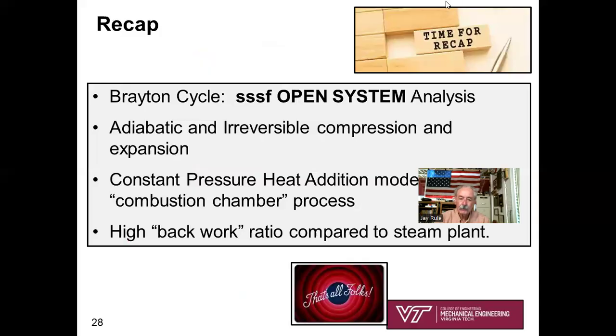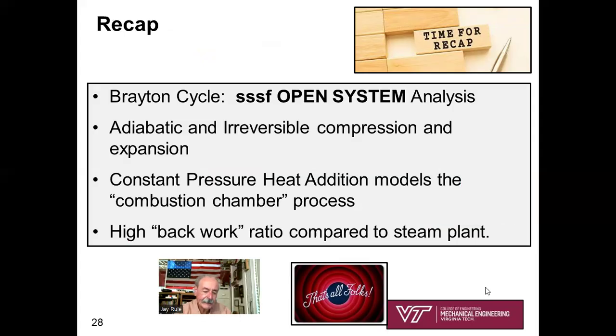So we've gotten to the recap of our gas turbine engines Brayton cycle. Recognize here that the Brayton cycle is dramatically different than our models for internal combustion engines. The Brayton cycle involves components that are open systems, steady state, steady flow.